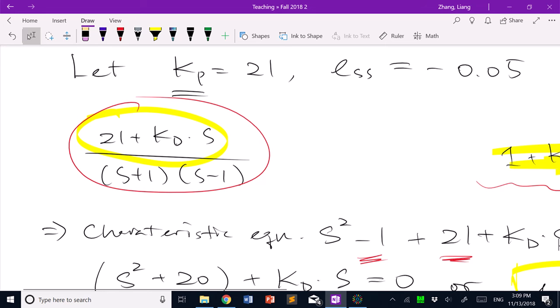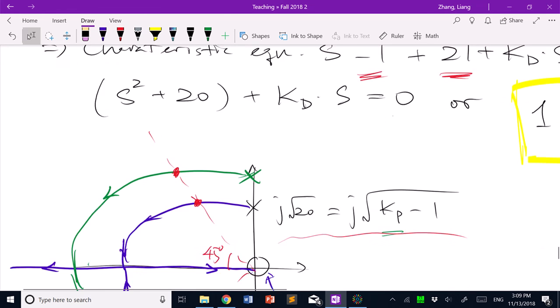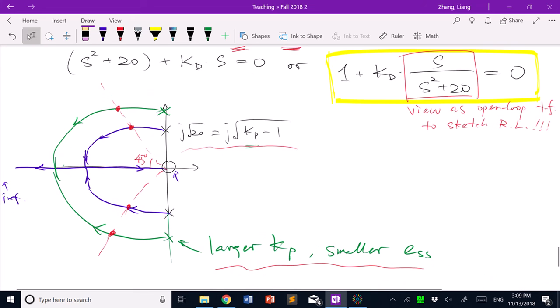But in this particular system, you will have a finite zero, so you want to be careful. Although this is how you choose your system, you want to plug the system into MATLAB Simulink and do a simulation and quantitatively evaluate the overshoot. If it satisfies the 5%, then you're good. If not, then you have to tune the parameters, maybe move it down a little bit, add a little more damping, such that you will have less overshoot. And that will be the methodology.